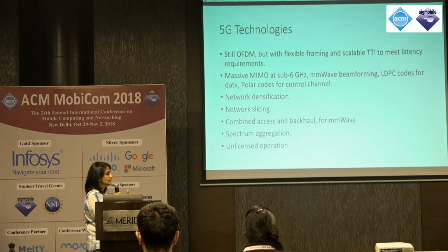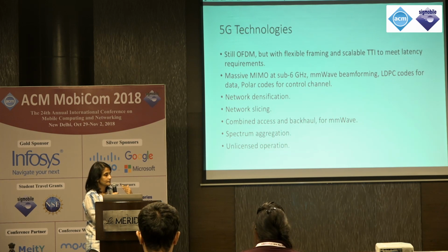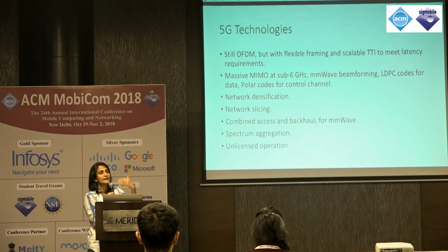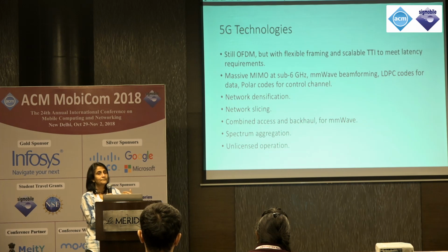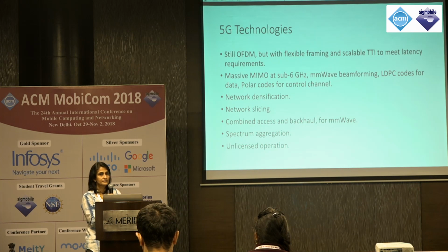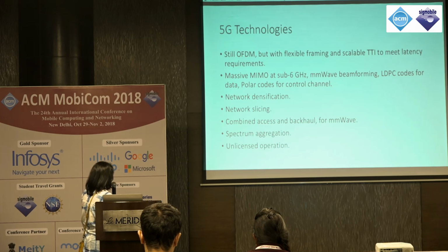The OFDM design itself is also scalable from the bands you're operating in. So millimeter wave OFDM, the numerology is different from the numerology in the mid-band, but it can still be designed, and the numbers are very related.